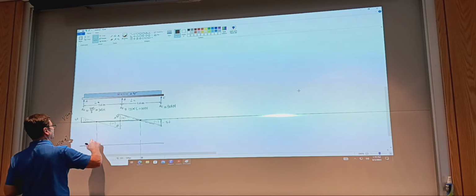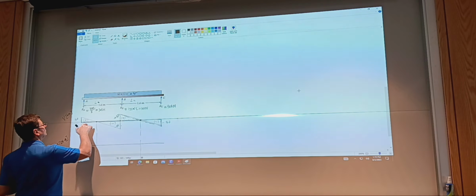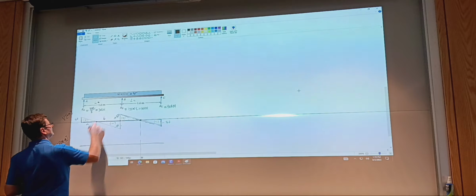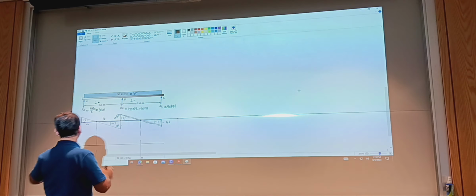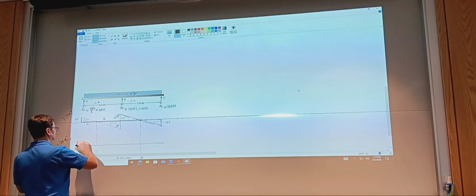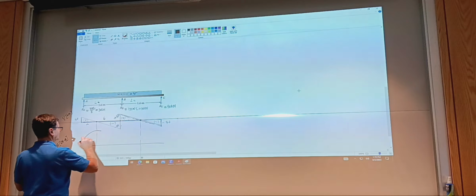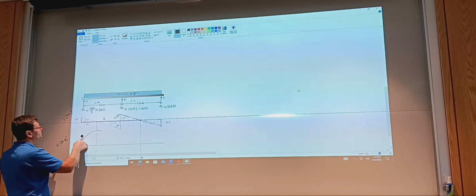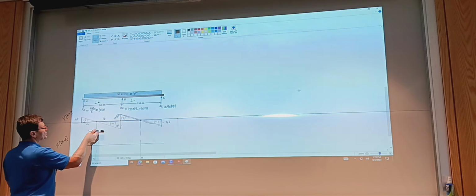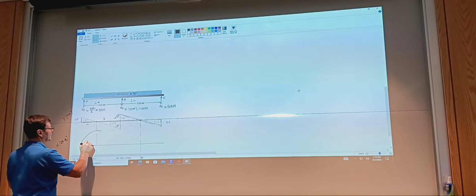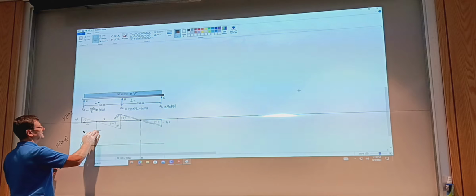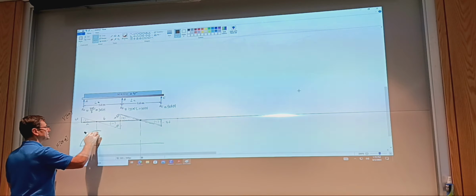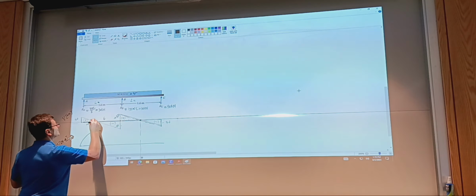And we can find that. I need to know what the max is. But again, the expectation is that the moment diagram will look like this. Okay, it starts with a large slope, which goes to 0. It cannot be this way, because then the slope is increasing, okay? So the max is again at this point.